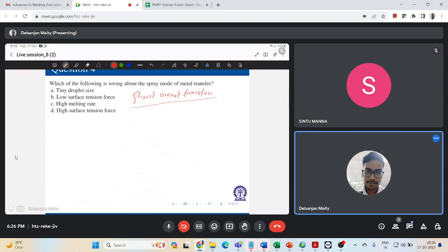However, due to the surface tension and electromagnetic force that I was mentioning, which will always be acting as opposing forces, the drop is pulled into the weld pool and the contact with the electrode is broken. This re-establishes the arc, right?